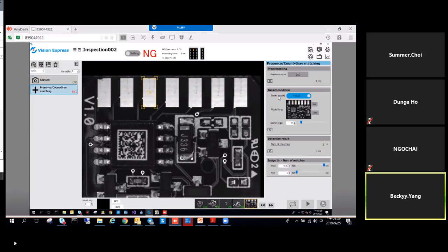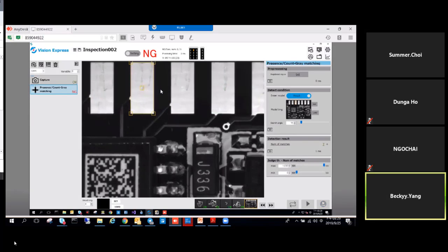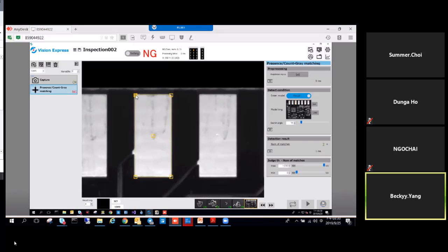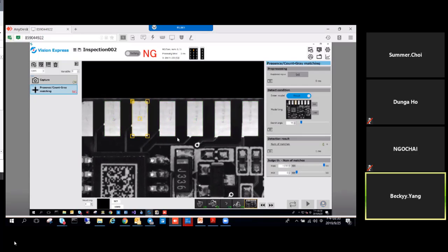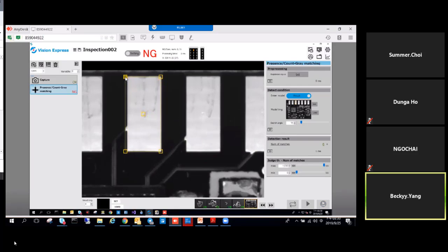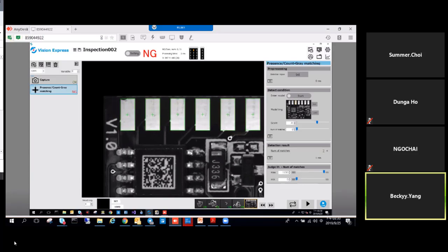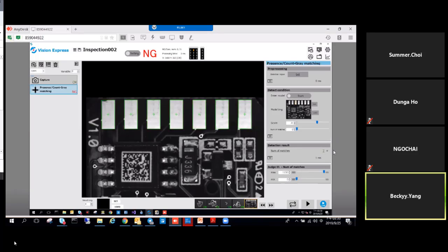So we can load the file and we choose the gray shape matching, and we open the start, and we drag the ROI. And because this Vision AV gray shape matching is to match all the pixels, we need to create it very accurately. It's better for the training model. So finish with set and finish. So we can find the 7 matches. You can see on the right.